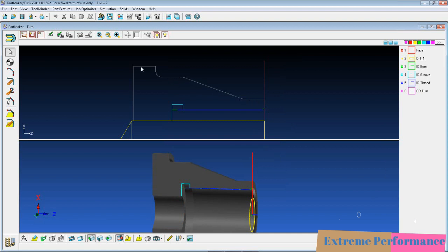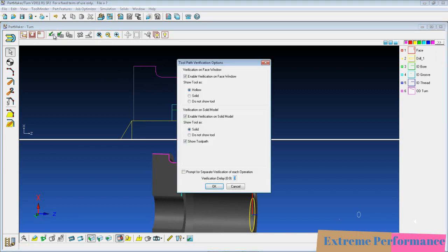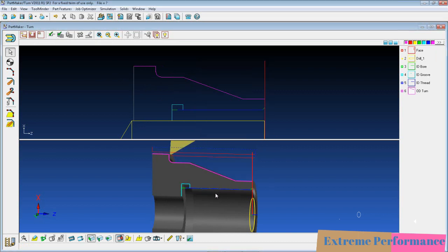So now to go through here, you can either use the define profile or the 2-point chain, either will work. I'm going to use the 2-point chain. So we'll start here, making sure I'm on the left side of the point. Okay, if you go down here, it could go the wrong way around when it does the chain. So start on the end, be on the left side, click one time, and you can just drag your cursor right to the end and click again, and there's our chain. Go ahead and verify, say OK.